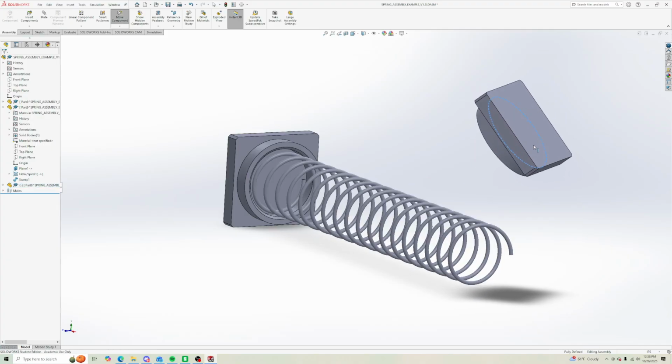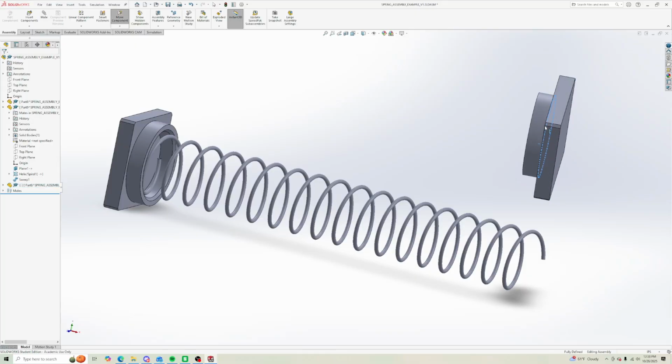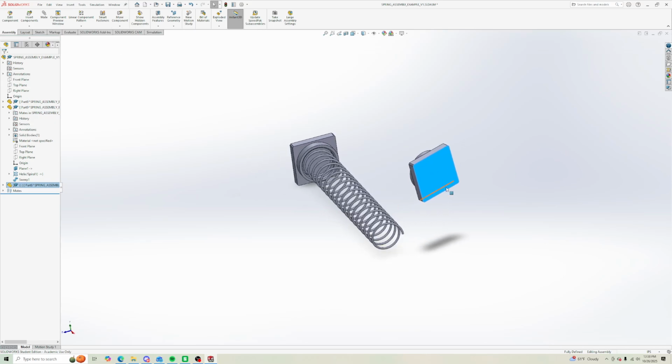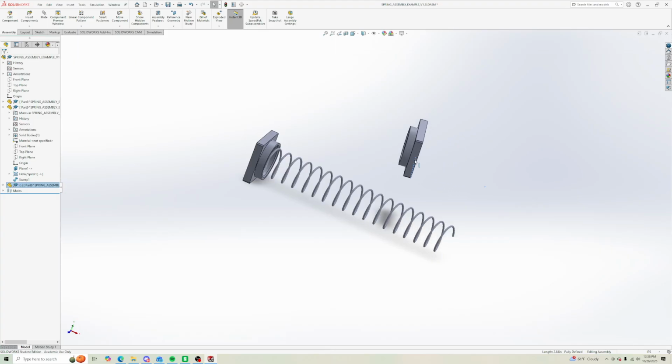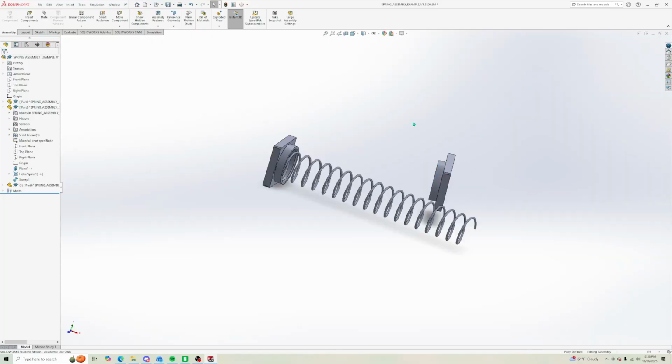So we're going to just kind of do our best at making it relatively lined up to where we're going to want it. And it wants you to put it off to the right over here. So what you're going to do with this is use some alignment tools. So hold Control, drag that to the right to make a copy of it. Then use the right plus drag to reorient.